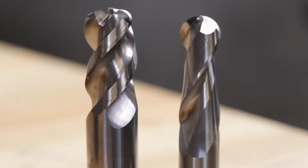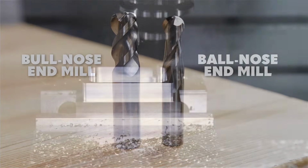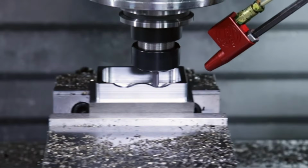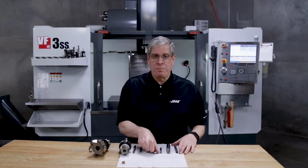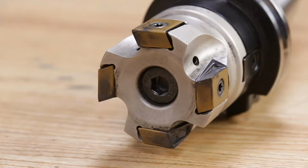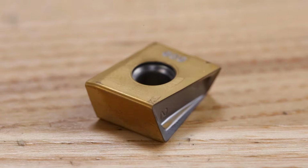End mills with corner radii are often called bullnose end mills. They also make them with spherical ends called ball-nose end mills. The spherical ends allow them to be used to cut all kinds of curved shapes. You can even get end mills made with tapered sides for special applications. As with drills, once you get above a certain size, it becomes more economical to use an end mill body with replaceable inserts like this.